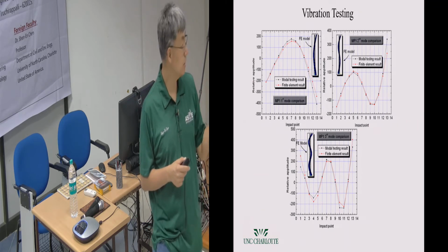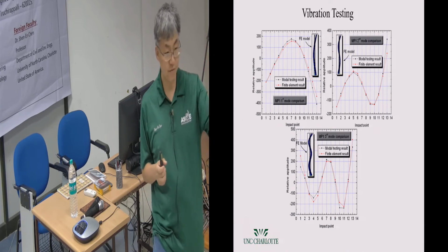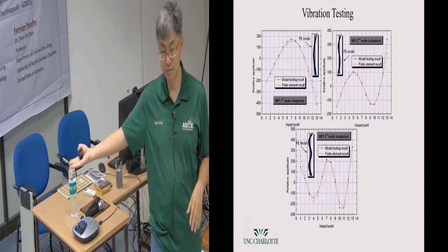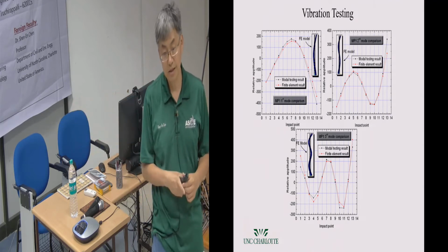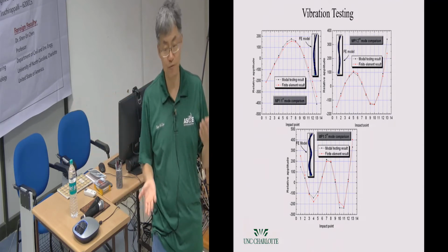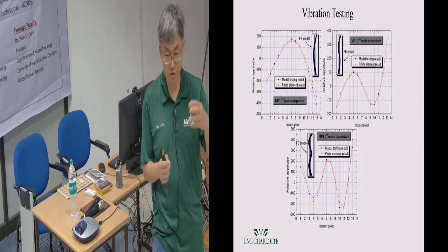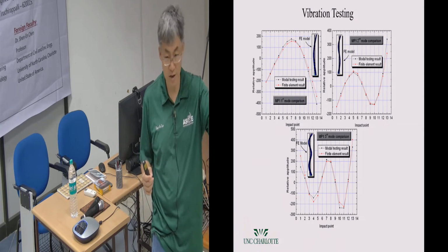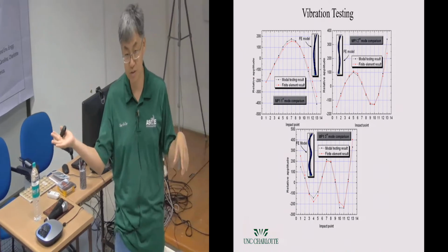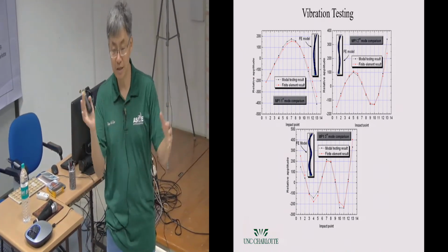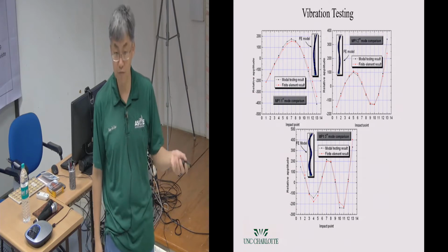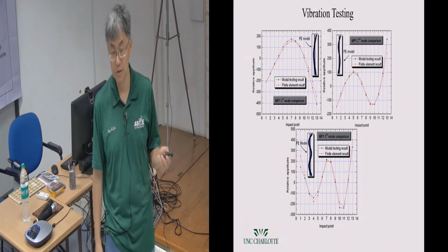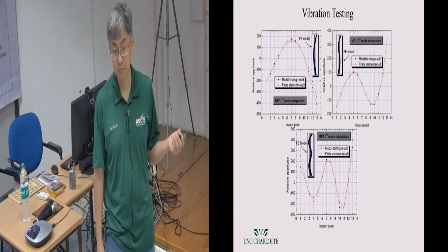But the other is, if you just have a finite element model and then you have the actual testing, because you're not certain about the boundary conditions, you need both. You need a finite element model to show you what kind of boundary is why you have this frequency. Then you do the testing and match the frequency. So a lot of times we have to build both the finite element model and the experimental one. Do you have any alternate methods to validate?